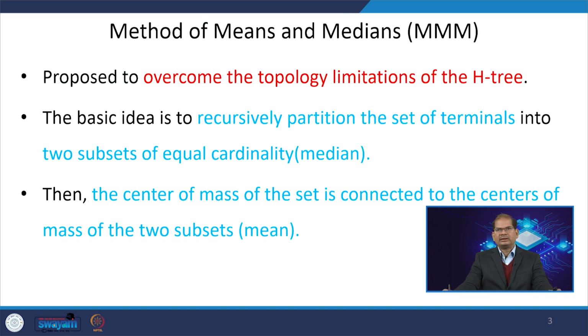So, clock tree synthesis is one of the important tasks for a VLSI physical design person. It is very important to understand how the clock tree is inserted in a VLSI physical design flow. The purpose here is to distinguish different approaches, because it will help us to solve the skew problem in the clock tree. So, the first most interesting algorithm is called the method of means and medians.